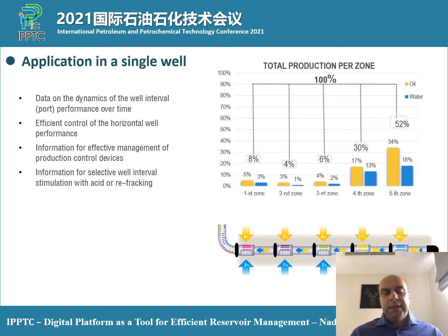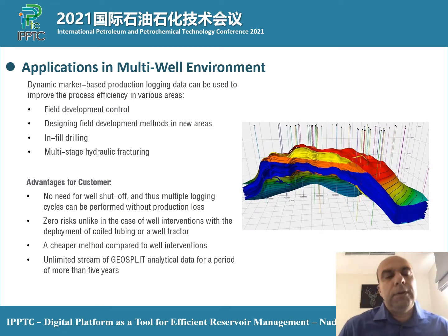It also can give a qualitative diagnostics to understand the work or performance of downhole control devices such as sliding sleeves, ICVs, ICDs, because using the traces in a single isolated compartment can quickly give the idea if the ICV or sliding sleeve is in open or closed position, where the water breakthrough or gas breakthrough is coming from, etc. Obviously, getting more dynamic data or big data allows the end user now to identify the patterns and definitely make better decisions in optimizing the field development, production increase, and ultimately hydrocarbon recovery.